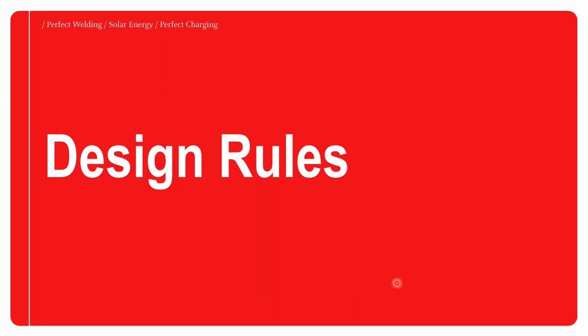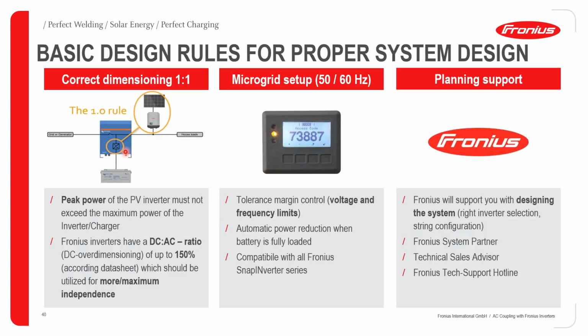Okay, so as David earlier mentioned, we're going to look at design rules. For the basic design rules for proper system design, please ensure that you obey the one-to-one rule, meaning that the peak power of the PV inverter must not exceed the maximum power of the inverter charger.